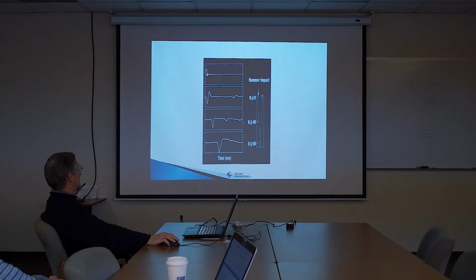And it's kind of nice. You see the initial hammer impact and the initial response of the receiver at the top. Then you see the response of the receiver halfway and the receiver at the bottom. So you can see this wave going down the shaft and then back up the shaft, and then back down again through this second echo. If we had a long enough record here, we would see another echo out over here from the bottom, the second bottom echo.